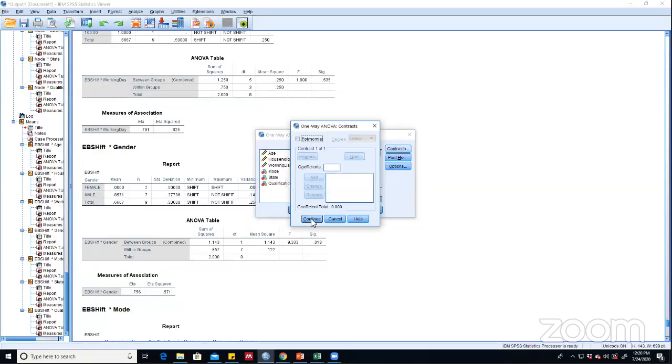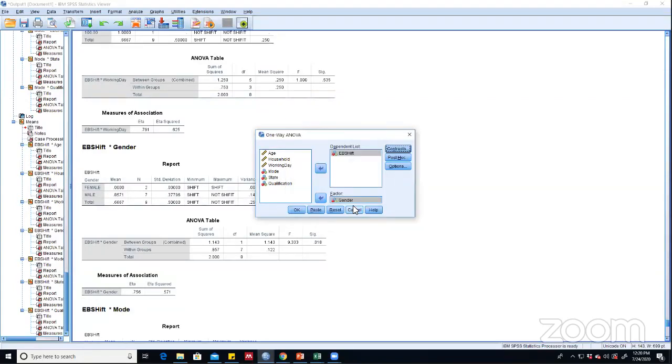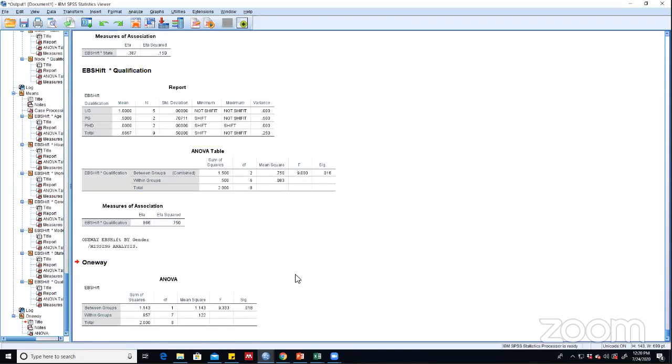But basically it takes one-way ANOVA, with the default 95 percent level, and you can click OK. So here you will get the ANOVA values, whether it is significant or not significant. Your F value is showing that it is a significant result. Like that you can interpret it.